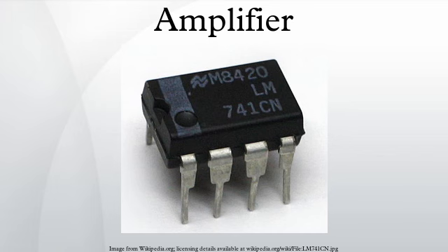Disadvantages of Class A amplifiers. Class A amplifiers are inefficient. A theoretical efficiency of 50% is obtainable with transformer output coupling and only 25% with capacitive coupling, unless deliberate use of nonlinearities is made. In a power amplifier, this not only wastes power and limits operation with batteries, but increases operating costs and requires higher rated output devices.